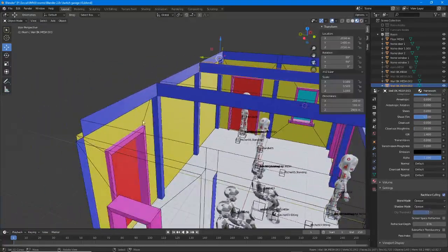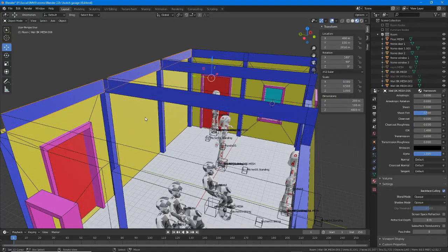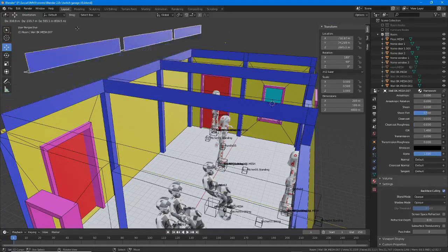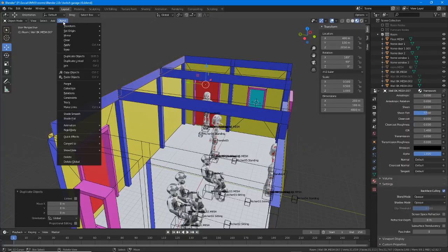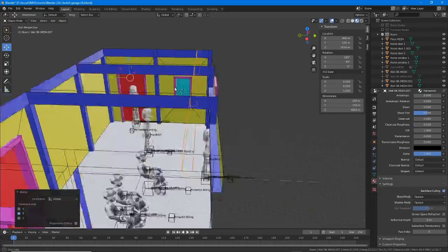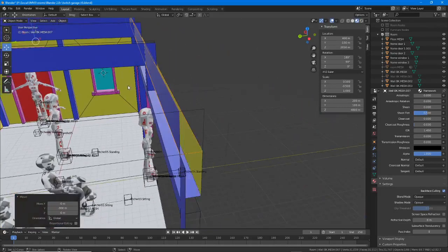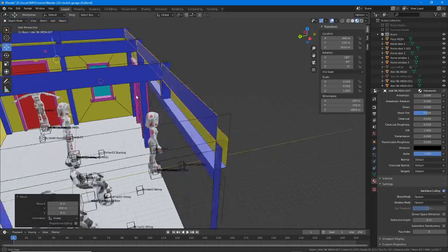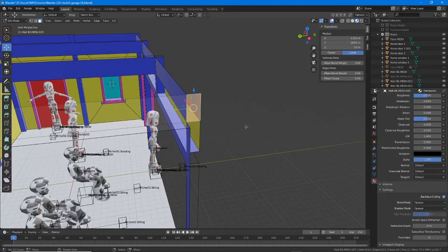And because we've done all that work, all we need to do is select that back beam, duplicate that, mirror it, and that is on the y-axis, I think. Mirror, y-axis, yes it is. Move that up to the front and repeat removing these corner faces.